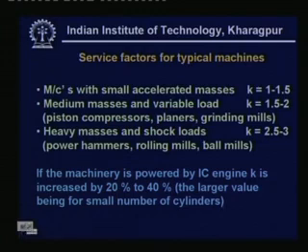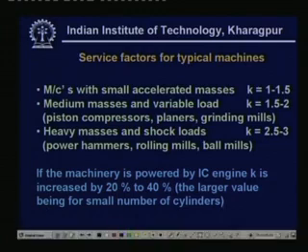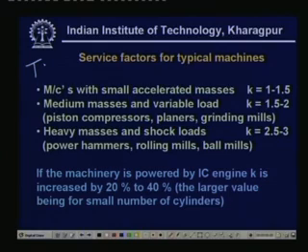Now, we come to one of the very important factors here, that is the service factors for typical machines. What is meant by service factor? Now, every time I designed with a constant torque, and how to rate this torque? This torque may be rated from the diameter of the shaft. So, this is the maximum torque which could be transferred, but usually it seldom happens that the torque is constant,